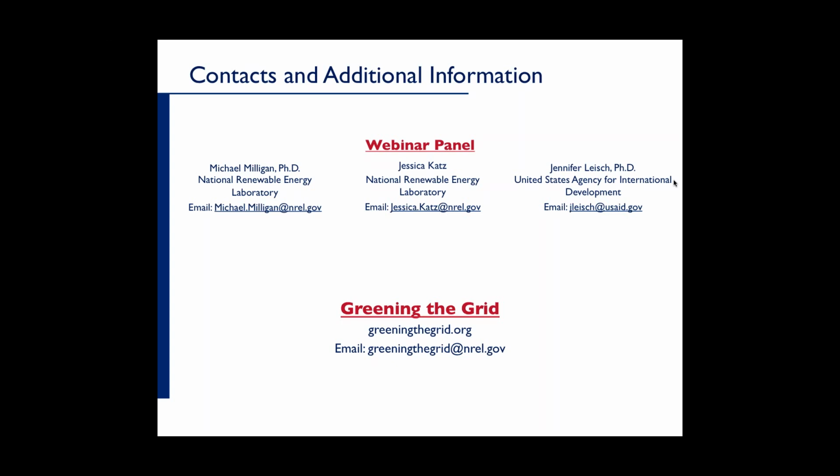And if that does happen, it will likely increase the cost compared to what you might be able to do in a larger system. I know that I'm not real close to this work, but I know there's a lot of work going on in Hawaii, really pushing the envelope on what you have to do for the system. And I know they have a bunch of old oil burners for generators that historically they have not operated in a very flexible manner. And so the question is, technically, can I change the way I operate those units? So I cycle them more often, turning them up and down. I turn them off more often, or is there an inherent limitation to the device?